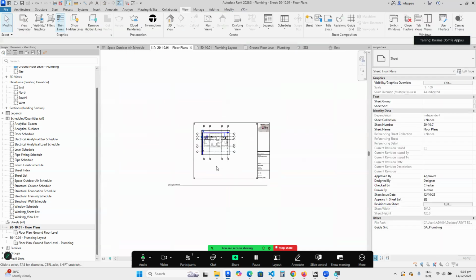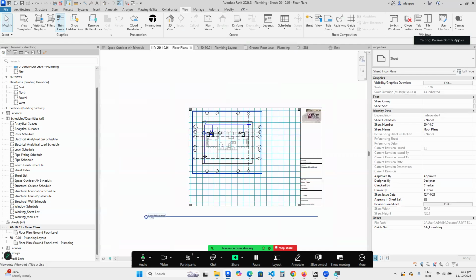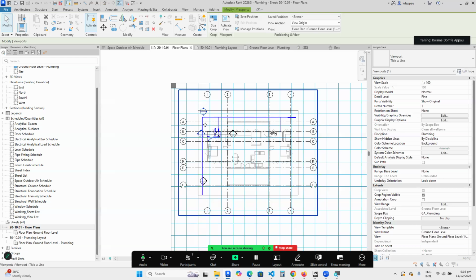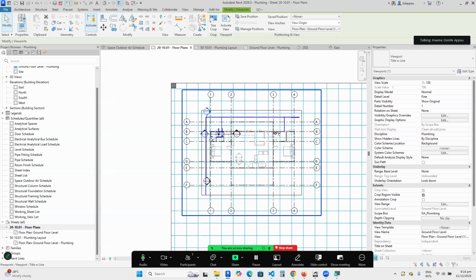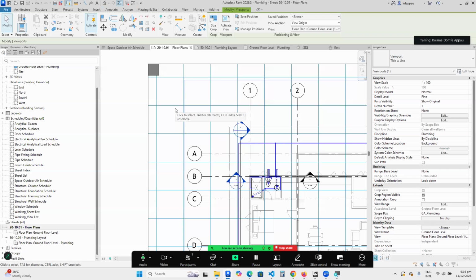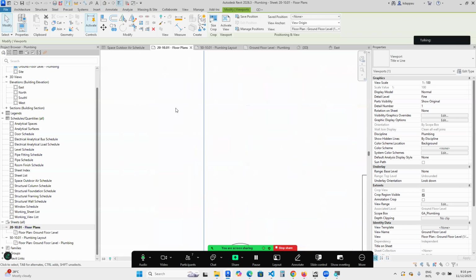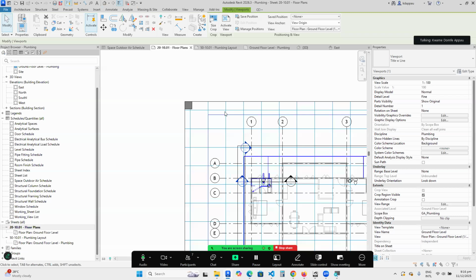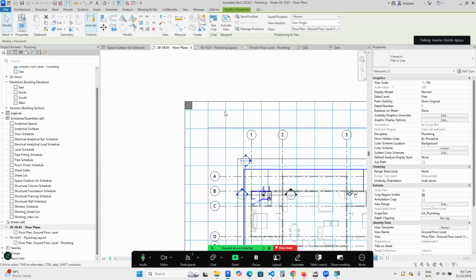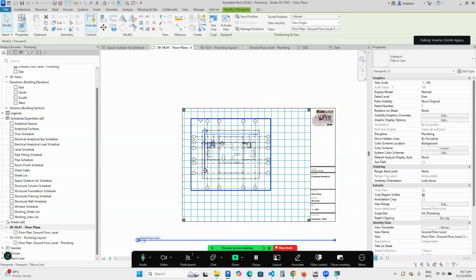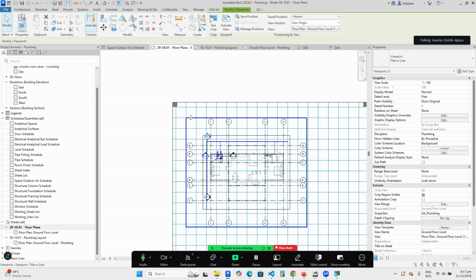So I have a grid that I am working with. Now if I select my view, I can use the arrow keys and adjust the side edge onto this grid. Then this edge at the top, I'll bring it onto this grid also. So I know that this view is placed from the corner of this grid here.